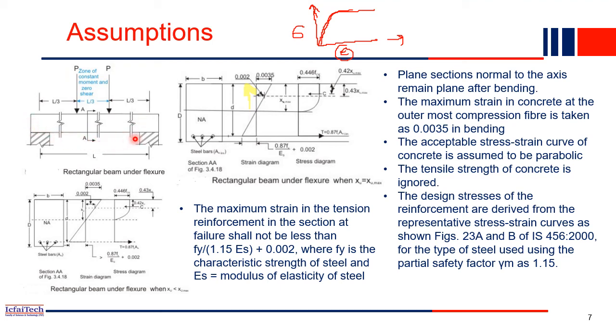This is a buckling shape. Now if you take a section at any point of a beam, the section will always be a plane section. There won't be any warping in the section. That we call plane section remains plane even after bending. So that is our first assumption.